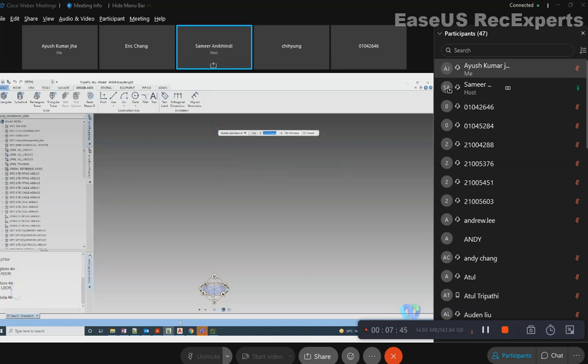So grid name is given. Now it is asking the grid origin, the bottommost point from which the grid will start. So let's give it, say, 1000, 1500 and 100,000 as the origin. So this is given.